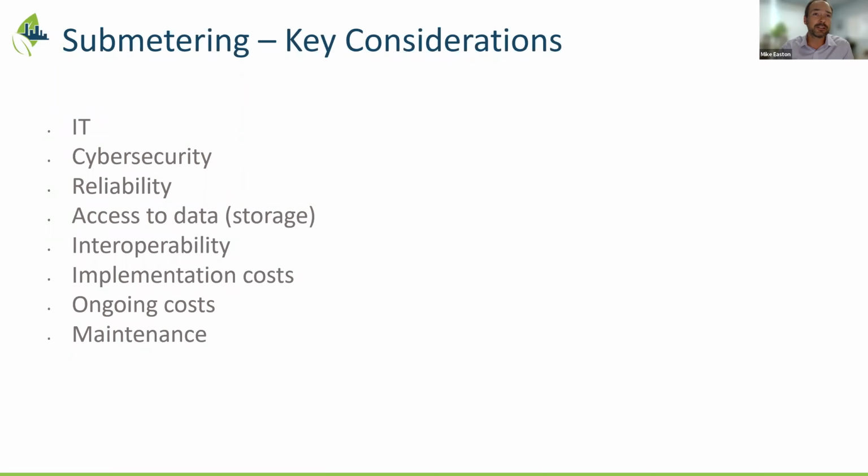So in institutional and commercial properties, we're really seeing Modbus and BACnet being the two most utilized open protocol solutions. There are some other ones that are still in some meter manufacturers, like HART and Profibus communications, but those are just not being utilized very much anymore. So I'd try to stay clear of those and really factor in Modbus or BACnet, which again seem to be very utilized these days.